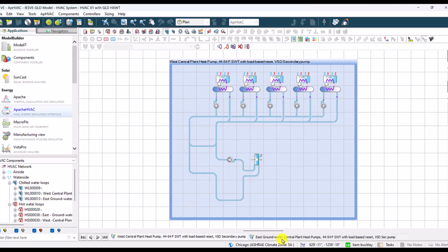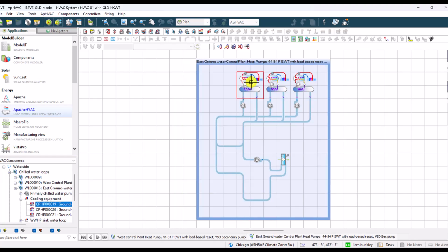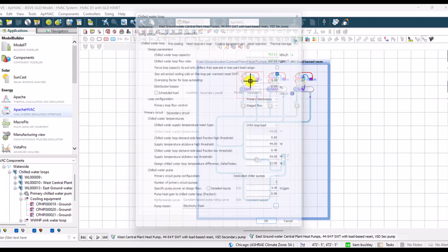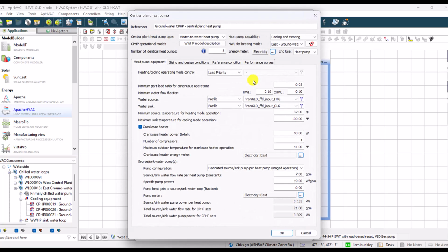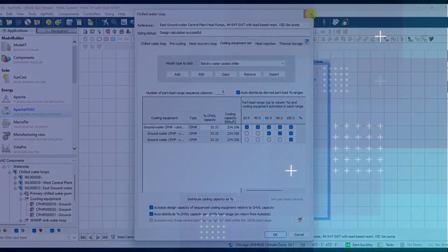that's the air-to-water heat pumps. I don't want that. I want the groundwater heat pumps serving this instance cooling coil and a chill water loop. So same idea, this time it's cooling or heating or cooling only. And that's why these need to be set up separately. If of course your heat pumps are reversible. If the ground source heat pumps are for heating only, then fine, you only need to address the heating side of the equation. So that's the component or equipment assignment of the groundwater temperatures.